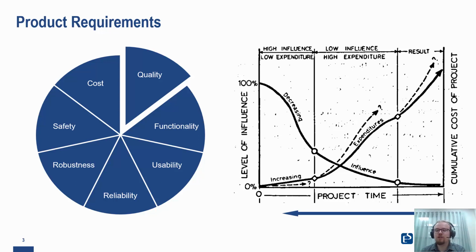Changing our tolerance specifications is much the same, also challenging, potentially expensive, especially if we discover quality issues during production. This can mean that we have to look at our tolerance specification again and identify any areas where we might be able to change our tolerance specification to be able to still meet quality targets when we aren't able to meet the original specification in manufacturing. Therefore, it is key that we get our tolerance specification correct.